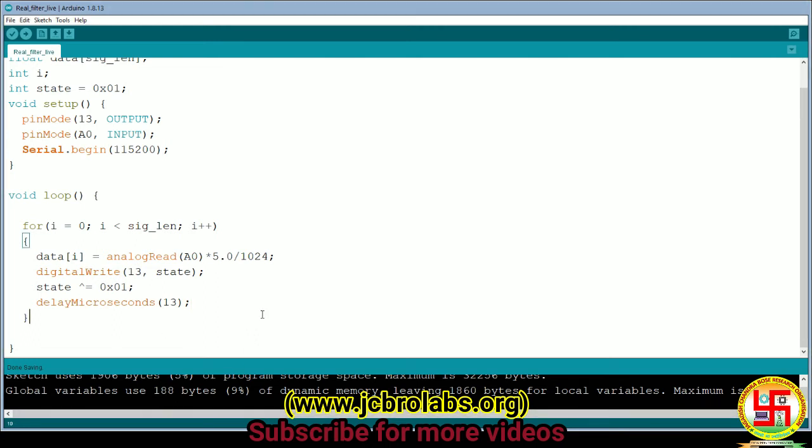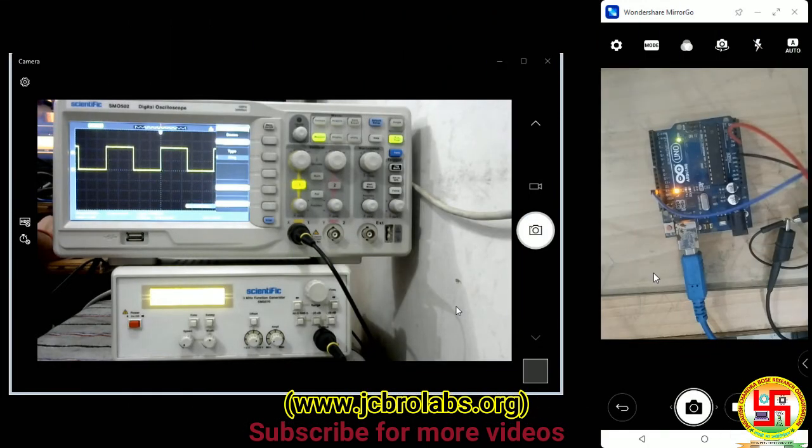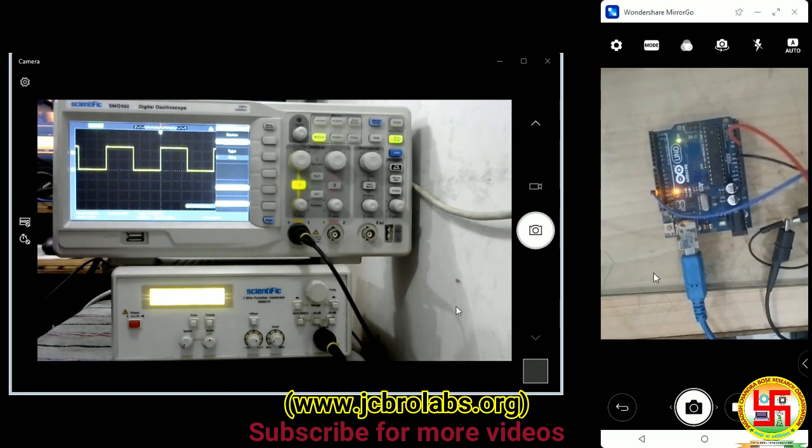Now let's burn it. Uploading done, and let's see the output of the function generator. So now the frequency of this clock is 3.9 kilohertz, which is nearly equal to 4 kilohertz, so the sampling rate is near about 8 kilohertz. So in all our computation, we will take the sampling frequency for filter designing as 8 kilohertz.